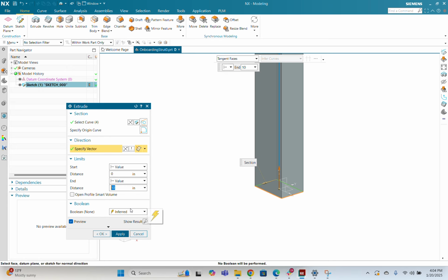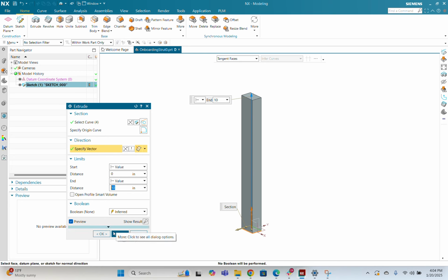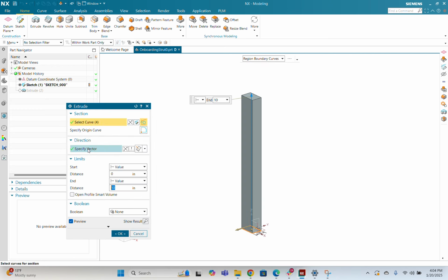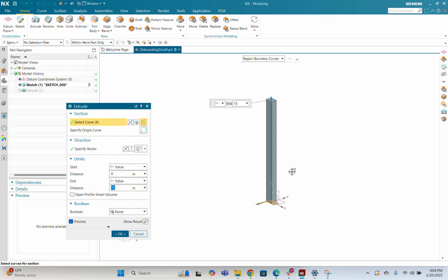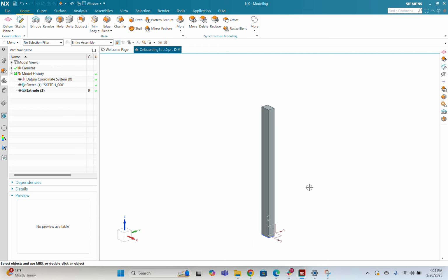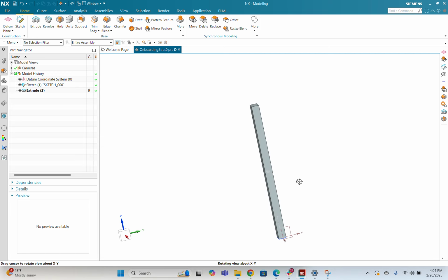Okay. There we go, there's my strut. I say okay, it extrudes it, done. But now let's say, oh wait, I actually meant to say I want this to extrude to 15. You can just double click extrude, it'll pull the window back up, and I can change it to 15. Just like that. Cool. So then I'll hit OK. And this is basically all you would need to do to make something like a strut in a basic design.